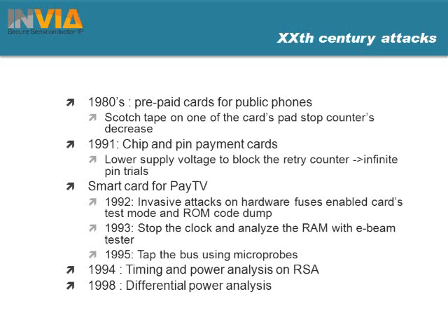So some people started to do fancy stuff. The idea was using the test mode of the chip, because in the test mode of the chip, you would have access to a lot of information that you don't have in the normal mode. So the goal was to access the test mode, and these clever guys managed to do it with invasive attack on hardware fuse. So basically, they modify the value of some hardware fuse, and were able to enter the test mode.